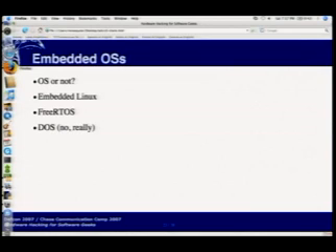Now, a lot of embedded applications will use while loops without a scheduler, but the way they meet soft deadlines is they do a timing analysis to make sure that each driver in the stack, when you're going round robin, is guaranteed to take less than the worst case time, and all the worst case times added together is less than the next time that a certain task needs to be executed.